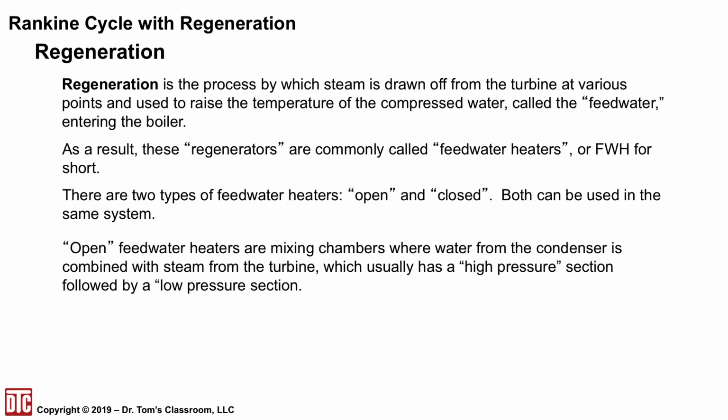Open feed water heaters are really just mixing chambers where the water from the condenser is combined with the steam from the turbine, which is usually at high pressure, followed by a low pressure section. So in this case, you have just two fluids coming together, mixing and coming out as one.